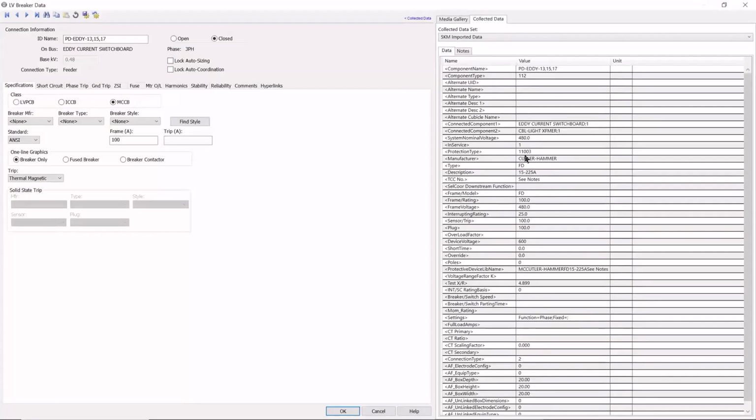This indicates that the manufacturer is Cutler-Hammer. So I can work around the missing data by mapping what I read manually from the dialog, the error report. And this will show me the part number. It helps to be familiar with the elements, but we're looking for something that's rated for 100 amps at 480 volts, 25K interrupt rating.